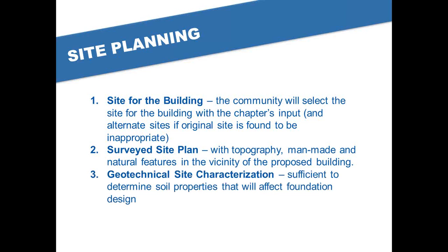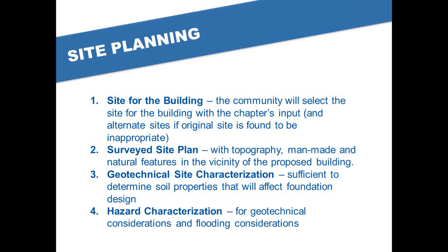Do a geotechnical site characterization sufficient to determine soil properties that are going to affect the foundation design. You're not going to need to do as much soil characterization as you would here in the United States, but you have to do enough to know generally what kind of soil you're dealing with and what its characteristics are.